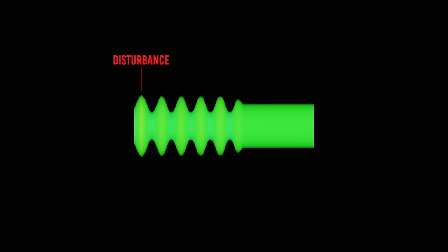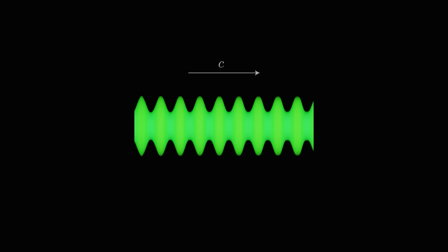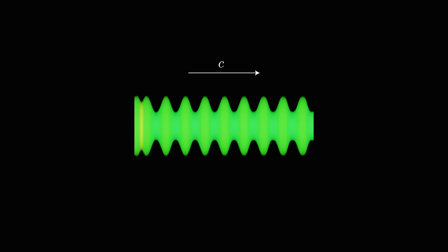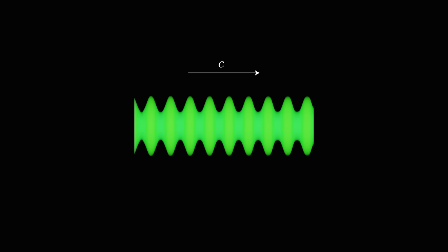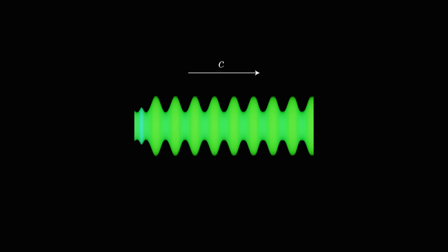So a disturbance at one end of the domain will not instantly affect the other end. This is not true for things like the heat equation, which predict that heat disturbances will be felt across the entire domain instantaneously. Instead, the disturbances travel at the speed of sound, unless of course the fluid is moving supersonically, but we're not going to deal with this situation very often.